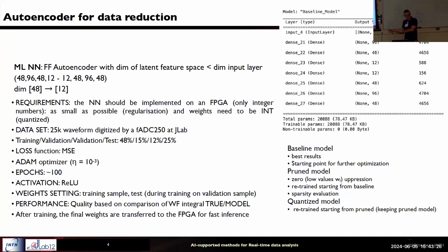Usually this is what happens normally. You do the training on CPU, on different computers, because for the training you don't really need to be very fast, but you do for the inference. When I am happy with my network, I take my weights, which is just a small file, and download them onto the FPGA, where I have the same structure, exactly the same nodes, and this is exactly the same as running on the CPU. This is the way it works. So at the end of the training process, I need my weights.